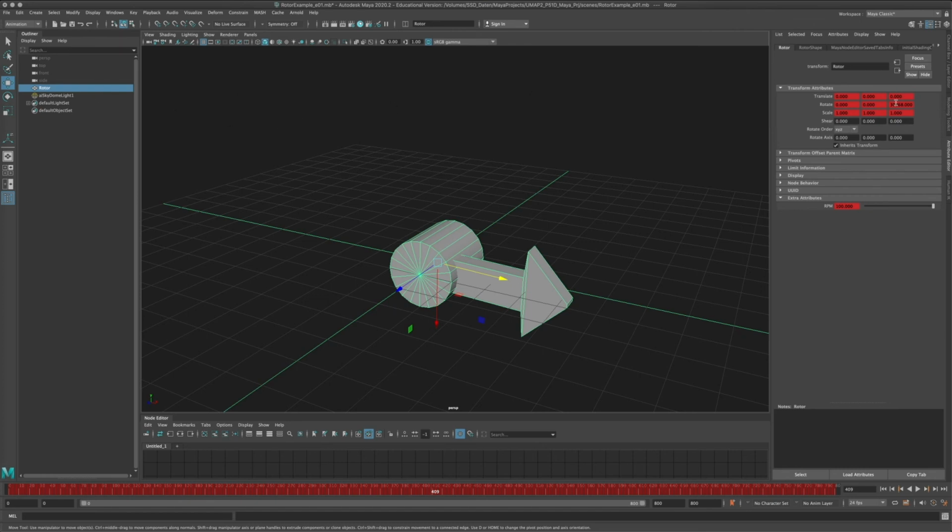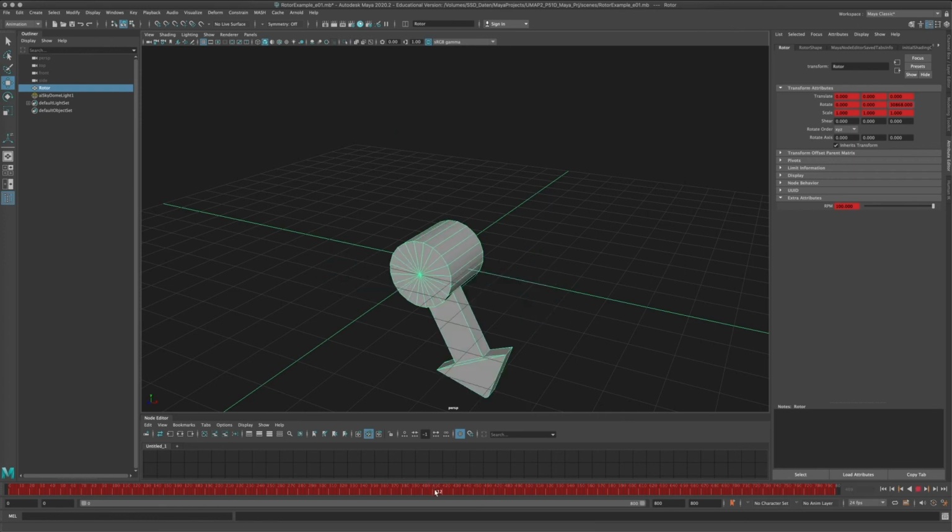So either you reconnect, you delete all those keyframes, reconnect your rig setup and have it that, or you keep a file as a backup before you've baked everything down, so you can go back and do your changes and then bake it down again and then re-render. So that's a quite technical thing, but still this applies to a lot of things that you can do in any kind of 3D software that will lead to problems at rendering stage.